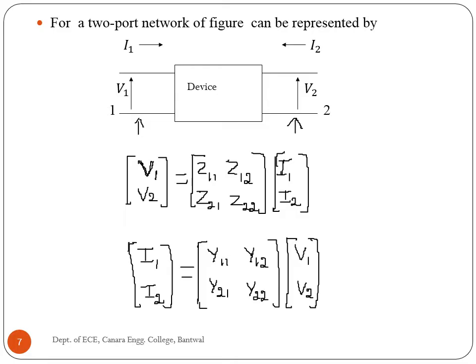Similarly, for Y parameters, we derive the admittance matrix by selectively stimulating each port with a voltage source and observing current at all ports. Once the admittance matrix is ready, all that has to be done is to multiply it by any new voltage vector to give us all port currents. Each of Z and Y parameters could be frequency dependent.